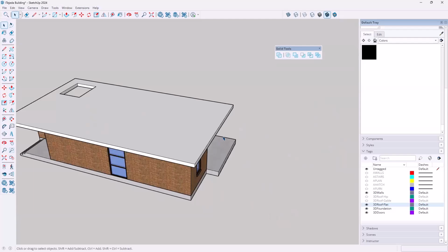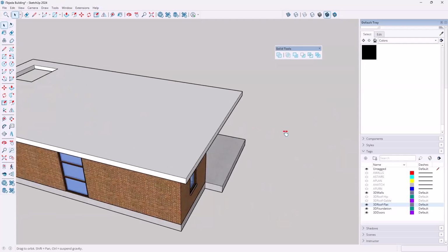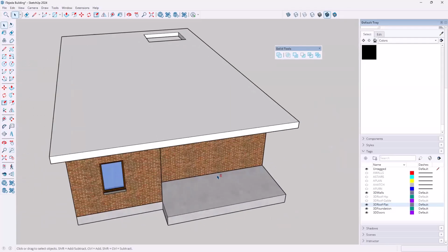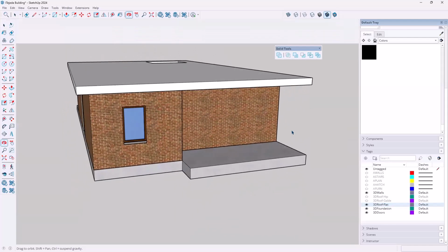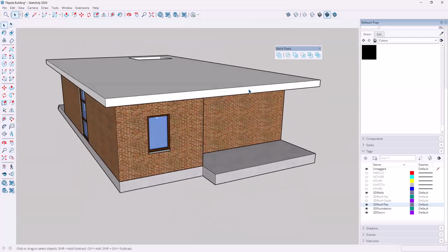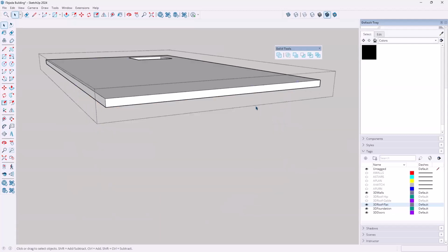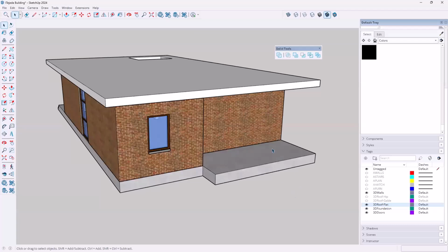If I come over here to the side, there's nothing stopping me from doing the following. Watch this. I know I was showing you all the roof types, but I'm getting a little carried away here. I want to show you how you can also be creative here. So I'll give that a double click. And hang on, before I do that, I'm going to measure the distance here from that endpoint over to this one, 18 feet. Okay, so I'll tap the space bar, double click in here.